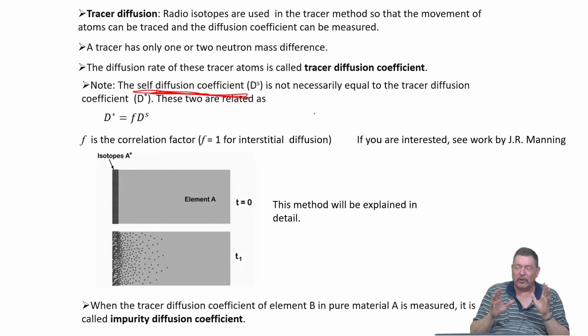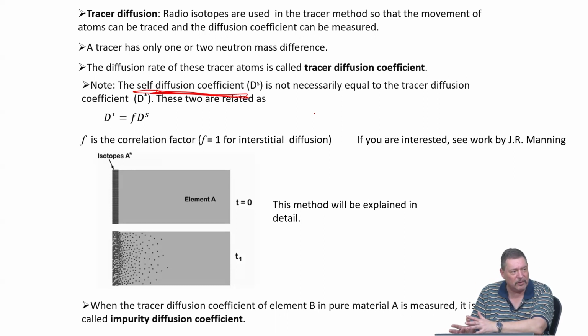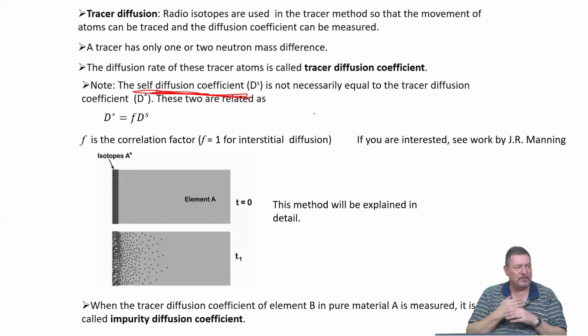But just to let you know, the tracer diffusion coefficient and self-diffusion coefficient can be transferred rather easily into each other, but they are not the same if substitutional diffusion is taking place.